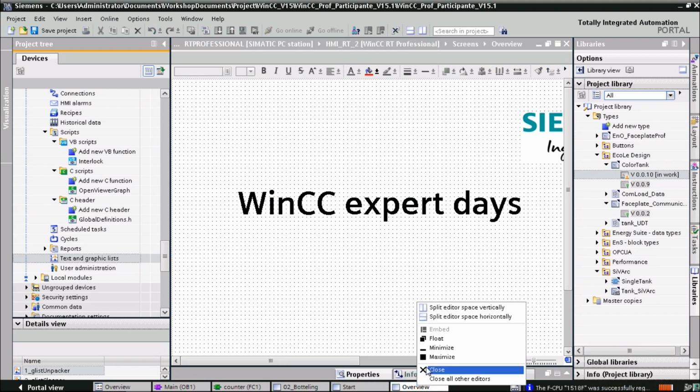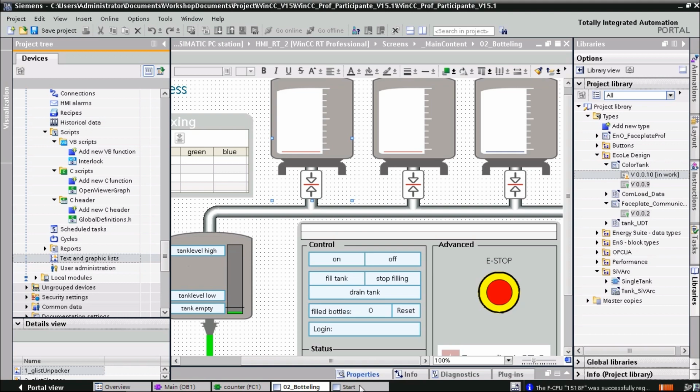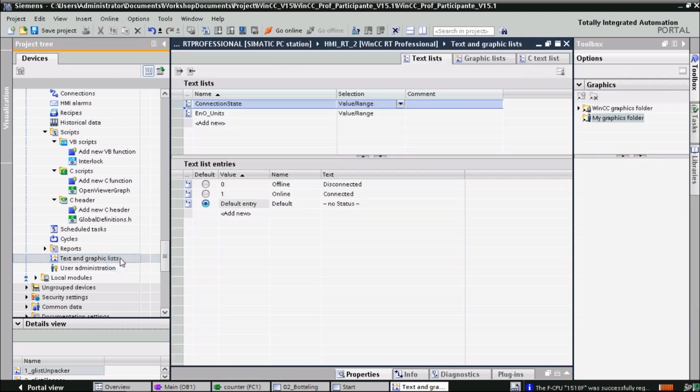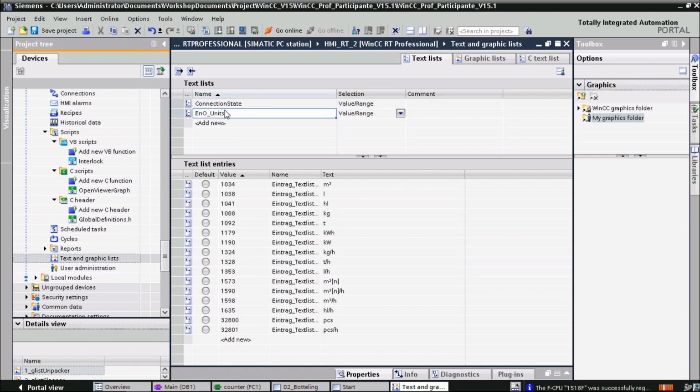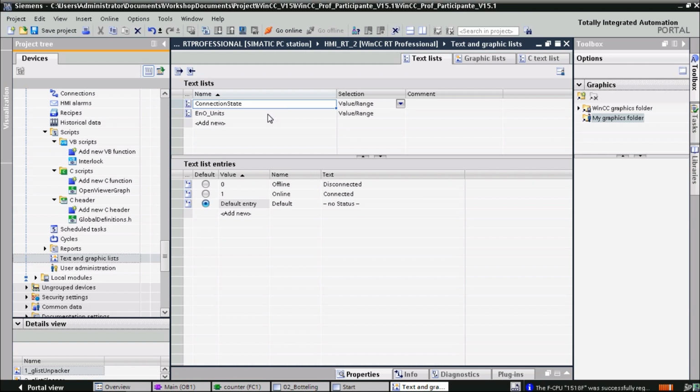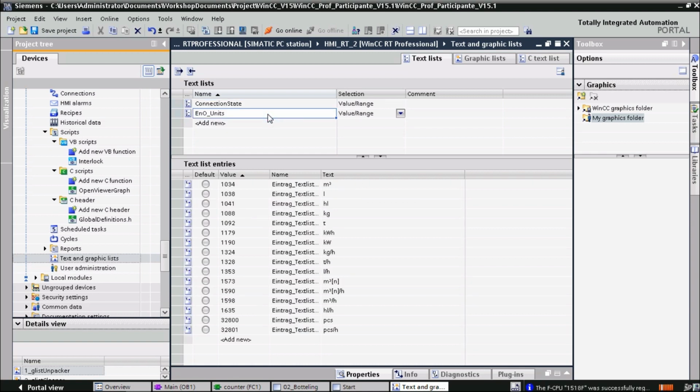I can also switch down here to the properties itself. You see here I can also change to full, date time, and then I see here already my energy objects, which are also existing in my project here. But when I go all the way down, I actually see that one tank underlying UDT I was mentioning in the beginning, which is also a type. So if I want to use a structure or a UDT in my faceplate type, the UDT also has to be a type. And I can also see the version behind it, because just one version exists for the tank UDT. I can then just choose this version. And when I connect it, I also see my elements here, which are color and content.